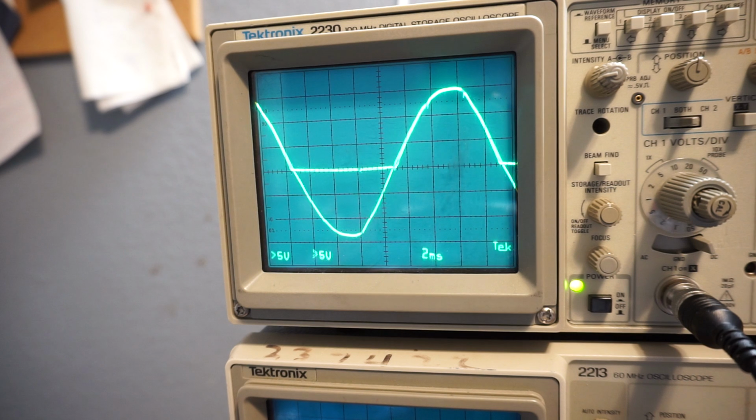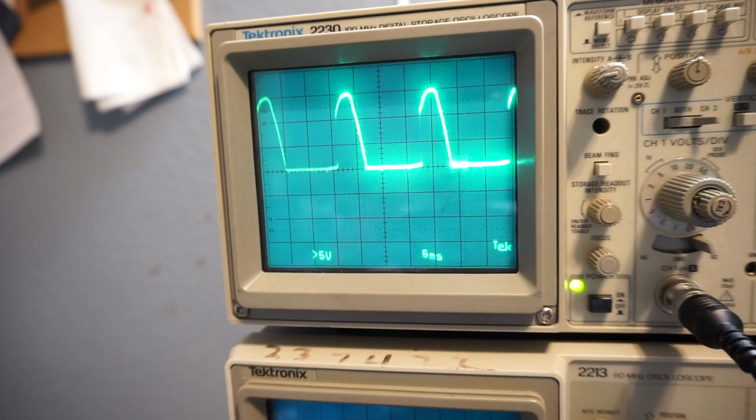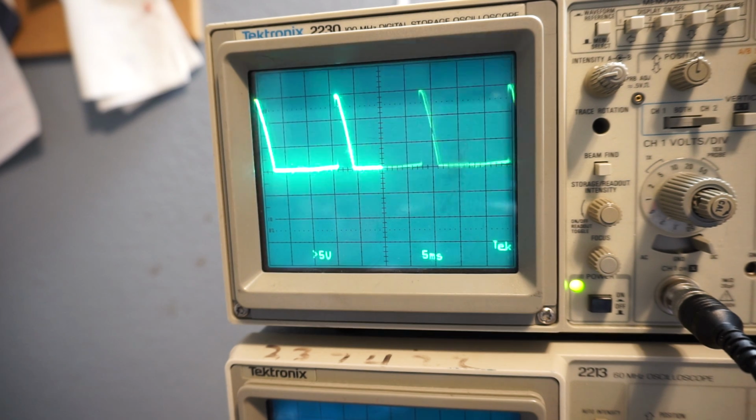When I turn this trimmer pot here, you can see that we can start cutting off a portion of our actual cycle. We can cut off part of the top half of our waveform, and this can be used as phase control. The way I have it set up, we can only cut off half the wave. I'll explain that in another video, but essentially we have to add some capacitors in there to do some phase shifting on our trigger line to actually get it to control the other half of our wave. So we can really only control a quarter of a full cycle with this right now, but that's a really good use of SCRs.